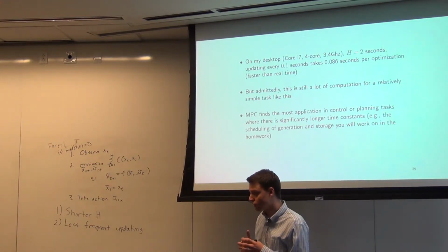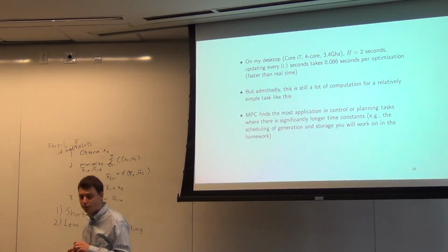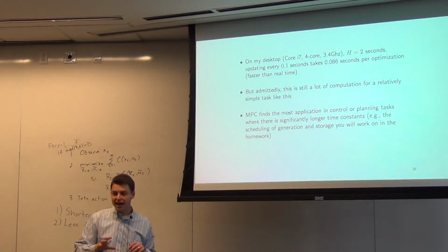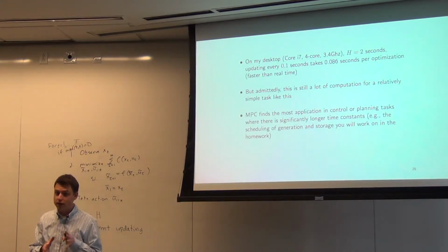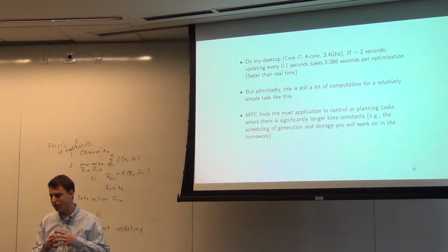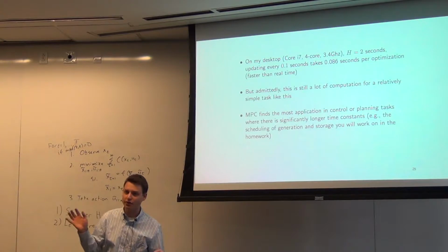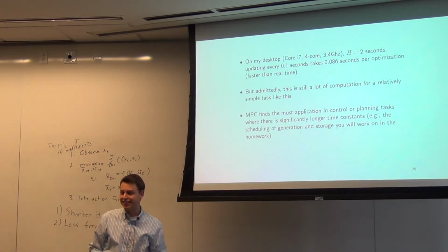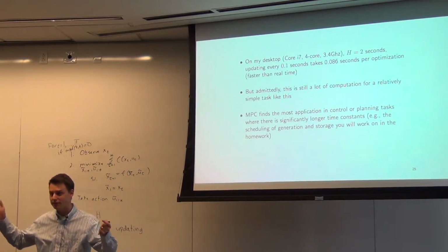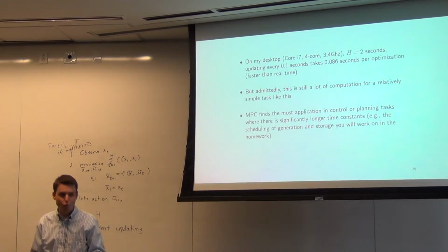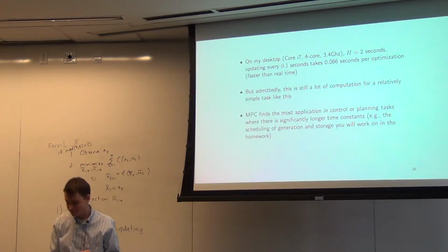So actually, one of the most interesting current directions, I think, in control is exactly this: finding domains where you can do MPC at extremely high frequencies to get this kind of optimization-based control, in a framework where typically that wouldn't have been imagined 10 years ago. That MPC was for controlling big factories, maybe, not for controlling a little robot or something like that, or not for controlling generators in a grid. It was for doing dispatch, but not for real-time control. But it's becoming more and more applicable to real-time control every day, every year.